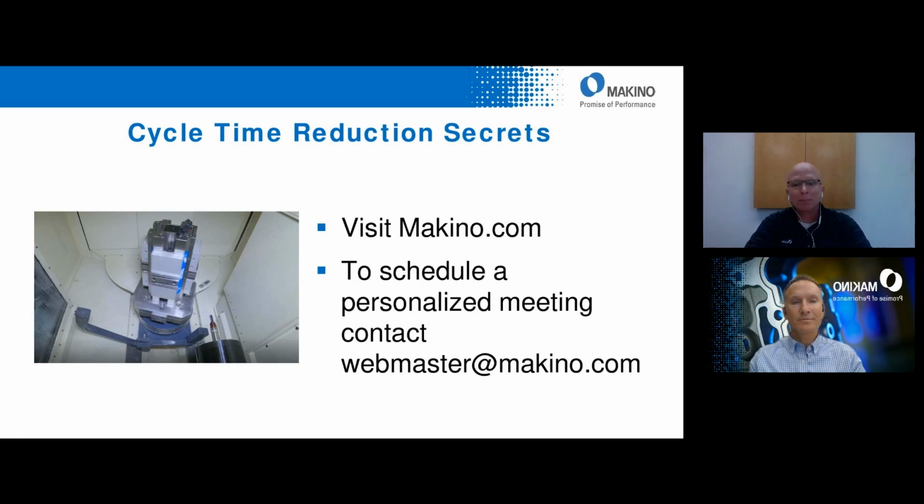Yeah, you'd absolutely have to be careful. I've seen instances where you implement the multi-axis positioning, and then you go to prove it out, and you're at 10% rapid feed rate override, just making sure that you're clearing all the features as you're positioning. And then when you go to 100%, the tool actually clipped the fixture, and that was because the rotary axis acceleration and deceleration is different than the linear axis. So it really starts with your simulation and your CAD CAM system.